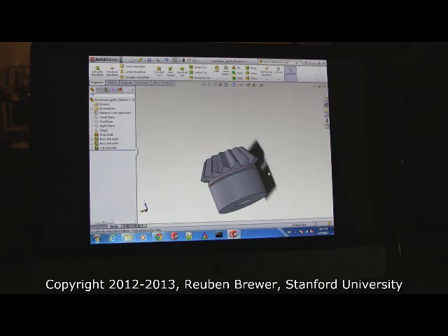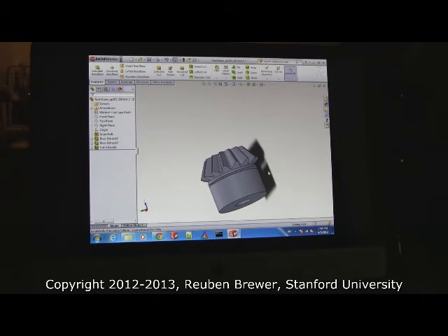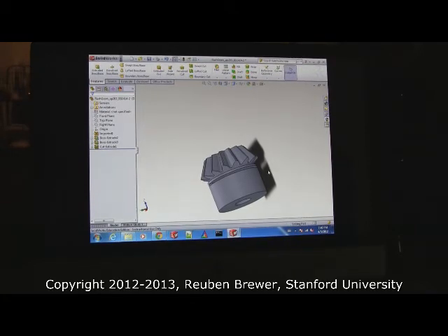I'm going to give you all a minute. I see some frantic clicking. What did you do after creating the yellow? Just type in the number 1 and hit the green check mark. Guys, another point, nothing in SolidWorks happens until you press the magic green check mark. Maybe enter, I don't remember. I always click the green check mark because it's safe. Has everybody got a cut? Okay.